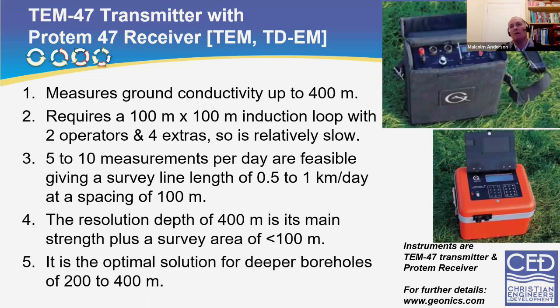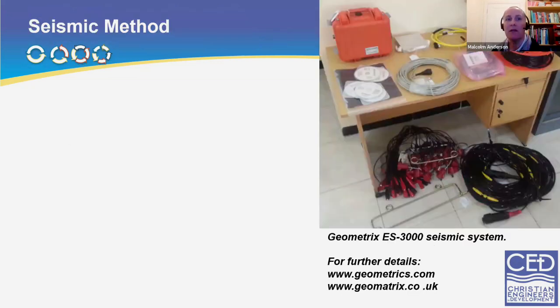So obviously this method is optimal for deeper boreholes or locations where the groundwater levels are quite deep, and therefore you need to know what's going on from the water level downwards. Disadvantage being the cost.